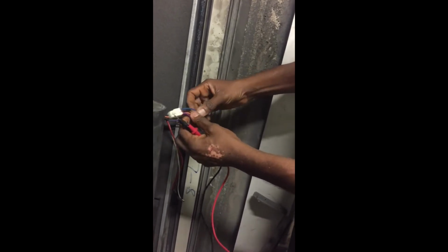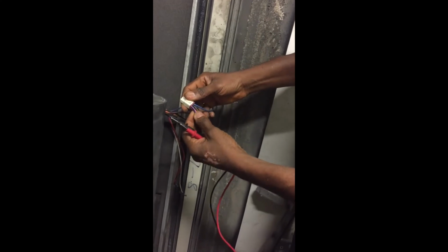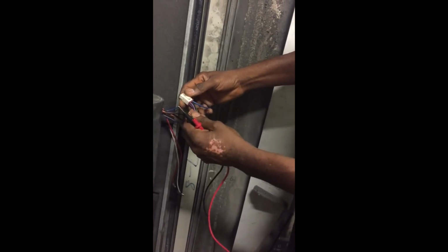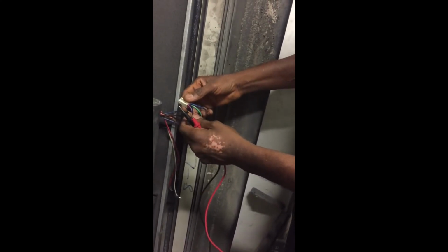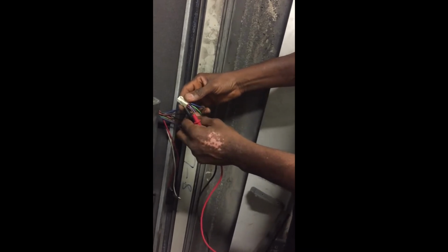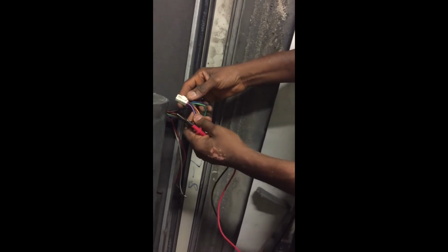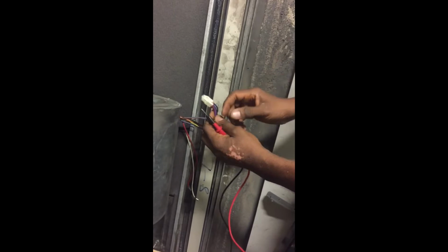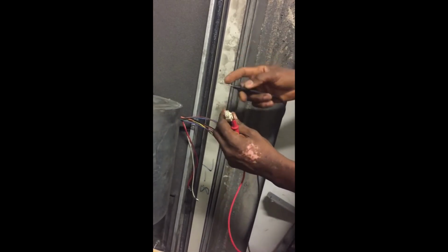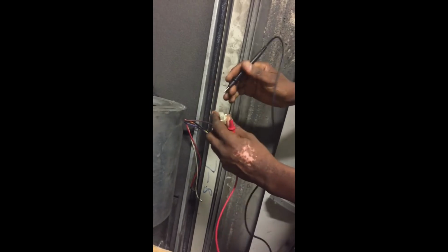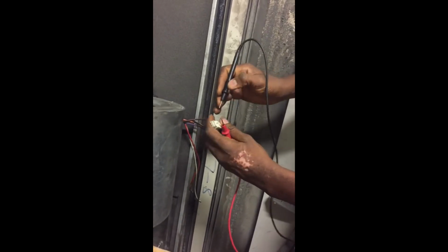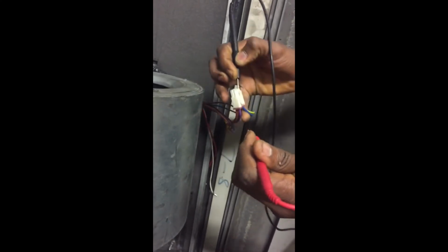I want to assume that these four, because in fan motors, most of the time black is always part of the speed control cable. So I want to assume that black, orange, and purple, and the brown are most likely the speed cables. But we need to start testing them since we are not aware of this. Remember, there is no schematic, so we are working blindly. If I assume that the blue is the common connection, then let me touch the purple.